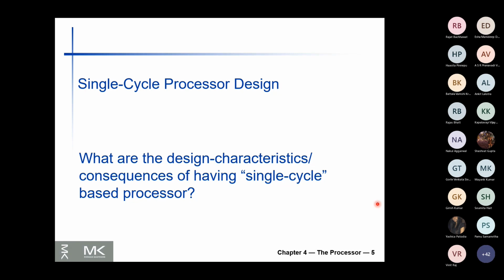Sir, every instruction has to be completed in one cycle. Yes, that means all the 5 stages that we have discussed, instruction fetch, decode, and so on. Everything has to be completed in one clock cycle. Now let me ask you a question here.